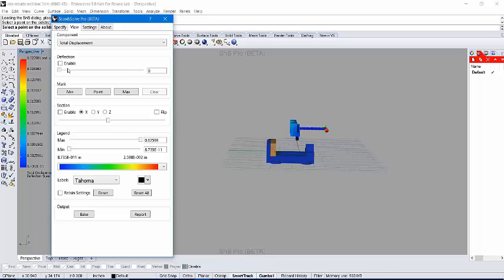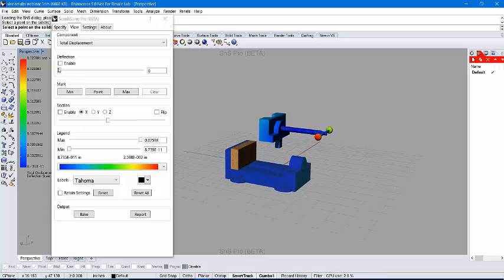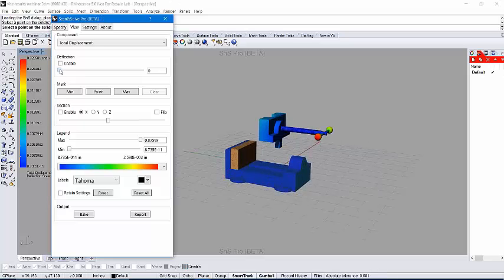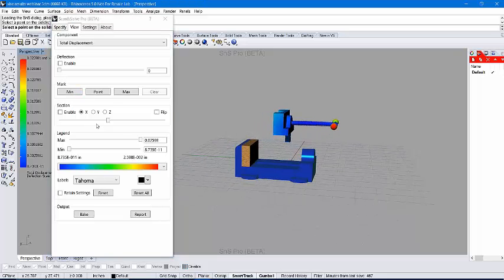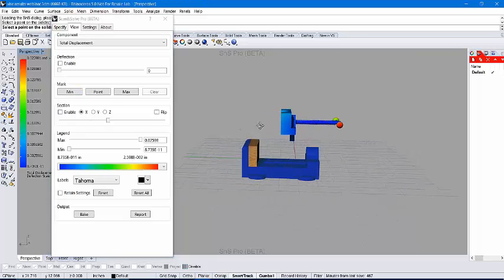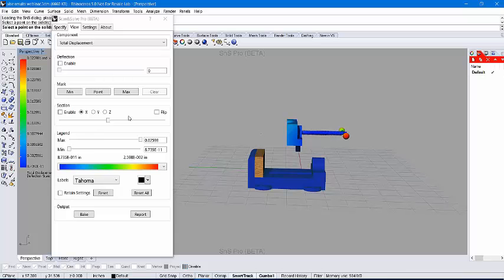As well, another feature you can use is to slide the deflection tab, and you can kind of see how the material will deform. And this has been implemented in previous Scan&Solves as well. But for those new users, this is a nice tab to kind of analyze how the material will deform. So some other features that are really useful, especially for analyzing stresses and strains, would be the section tab.